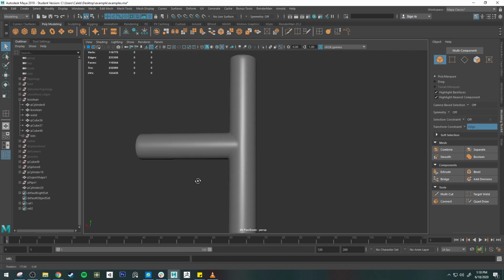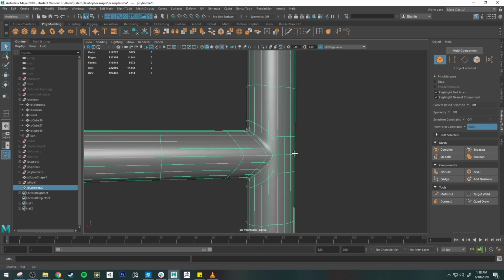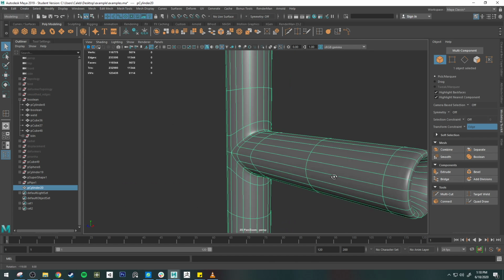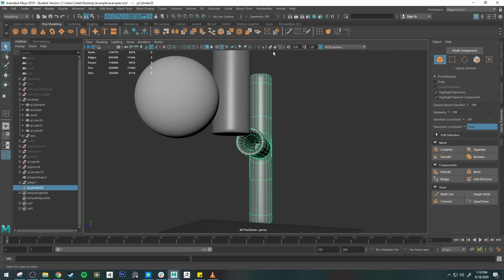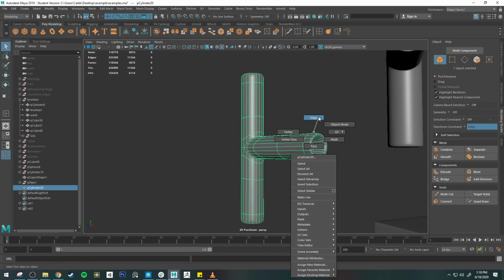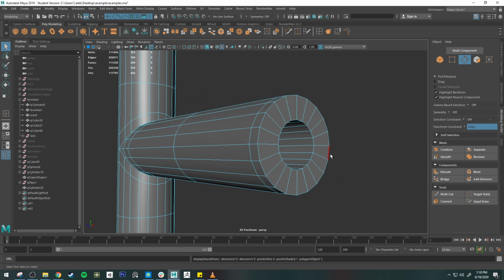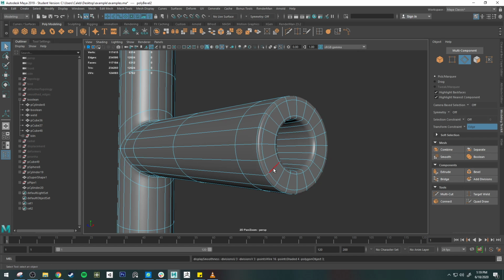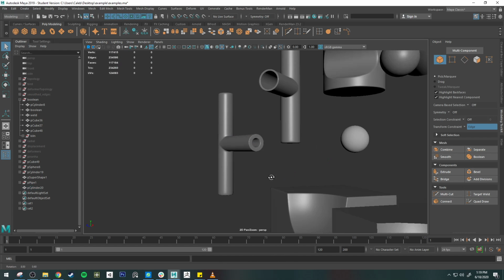Okay, and so now I have this fairly nice weld. I didn't worry about the other side because I have that n-gon. I didn't clean up that area, but I can just easily cut my mesh in half and mirror it, right? And then I'll go ahead and add some bevels to my object. So grab these guys. And this isn't part of the Boolean cleanup process, it's just me being more nitpicky about this.